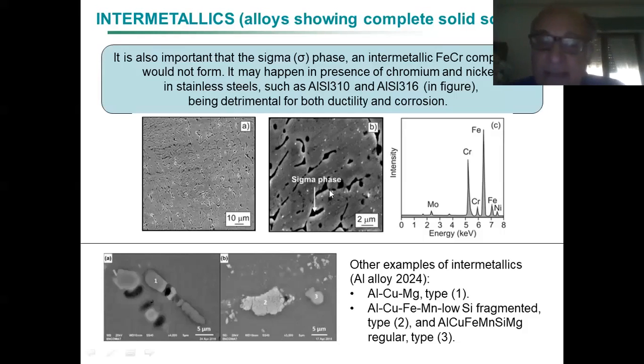You can see, as always, the X-ray diffraction curves, which show you what is the situation. You have some peaks. Of course, the highest peak is for iron. We can suggest that the two relevant peaks are two different iron phases. I might suppose that the highest one is alpha iron and the lowest one is gamma iron.